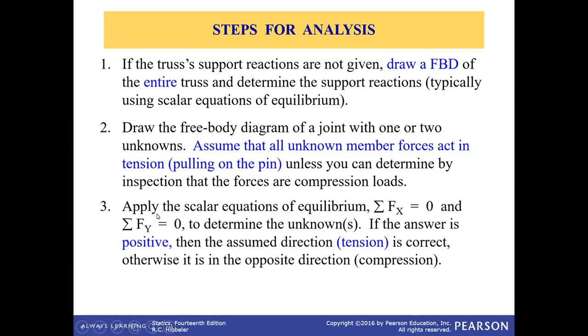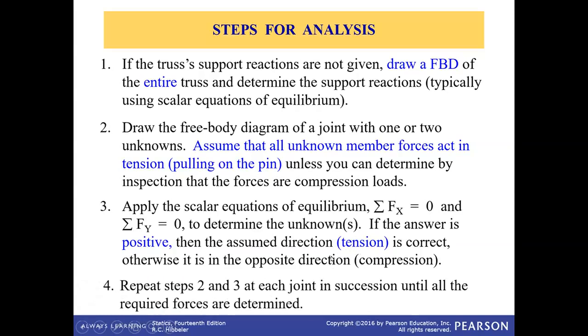So, pulling on the pin. Apply the scalar equation of equilibrium. This is again from chapter 2 and chapter 3 that we have learned: sum of the forces in x equal to 0, sum of the forces in y equal to 0, to determine the unknowns. If the answer is positive, then the assumption is correct. If the answer is negative, then the assumption is the opposite.